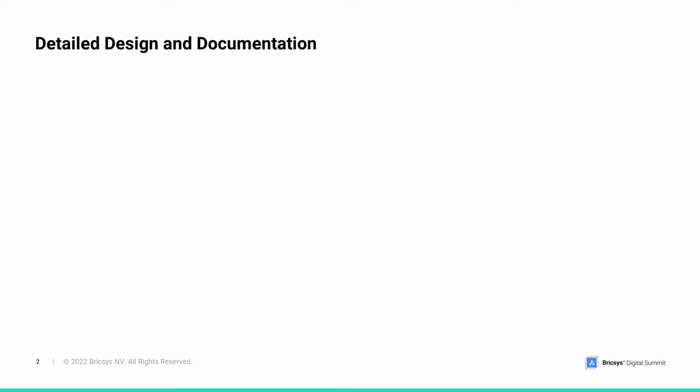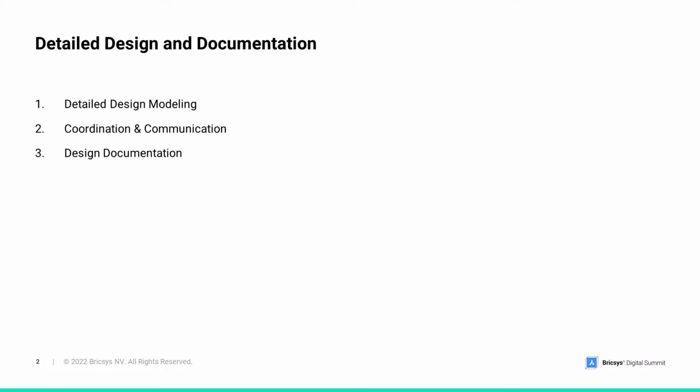We will talk about 4 steps in this process. We'll start off with the detailed design phase, where the model is refined with more detailed geometry and data. We'll also talk about collecting data from different sources and collaborating with different stakeholders by means of open exchange formats and issue management platforms. Next, we'll cover the creation of a 2D documentation set. Plans, sections, elevations, and schedules are all important documents that can be extracted from the model. Finally, you may need to include 2D deliverables to make your set complete.